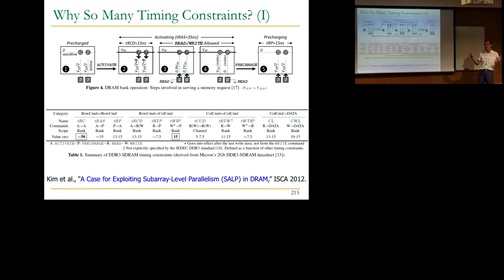That interface doesn't exist today in the memory controllers that we have. That may be a much more flexible interface, as you can see. Right? This is a very rigid interface. Somebody needs to specify these timing constraints, and DRAM needs to obey it, and memory controller needs to obey it. It's basically everybody designs things separately. Whereas the other interface, asynchronous interface, is perhaps much better. It's more of a handshake protocol. You send a command or send a request, and whenever the DRAM is done, it sends it back.